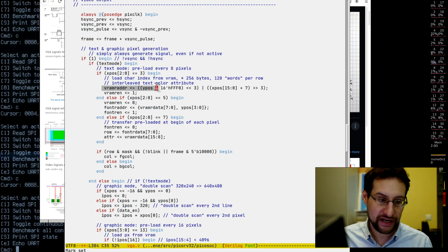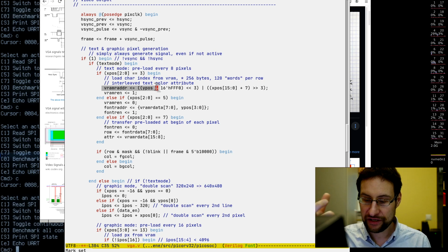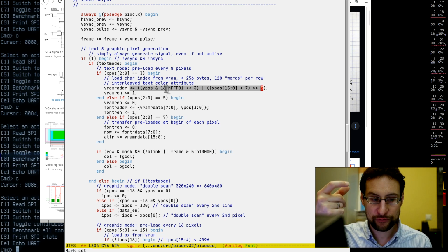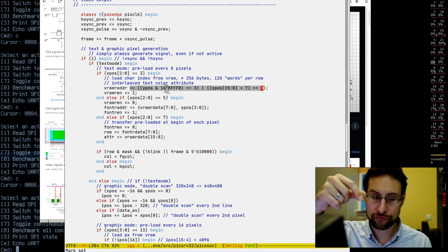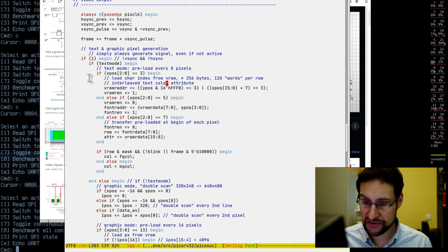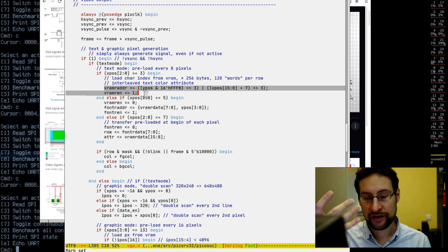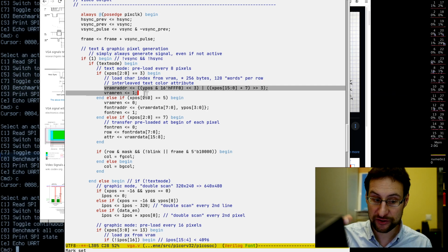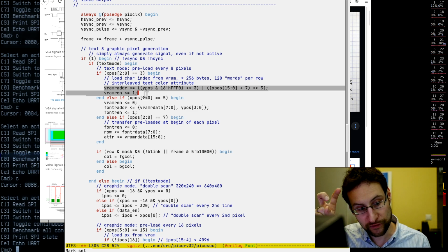So we assign the VRAM video memory bus address to the position where we load from, like the X and Y position. With text and attribute, 0 is text and 1 is the attribute, so 0, 2, 4. This is a VRAM address. And as we learned the hard way, it does not come out instantly. This is why it is 1 clock cycle delayed in our example: because we double data rate this, we actually need 2 clock cycles, since we overclock this a little bit here.